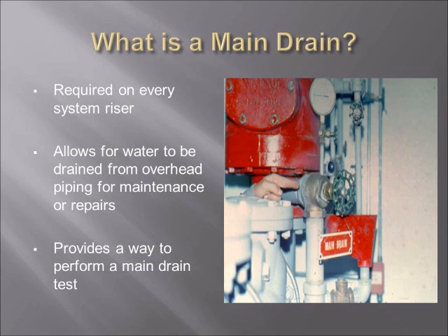NFPA 13 mandates the size of main drain connections, with the most common size being a 2-inch drain for risers that are 4 inches and larger.